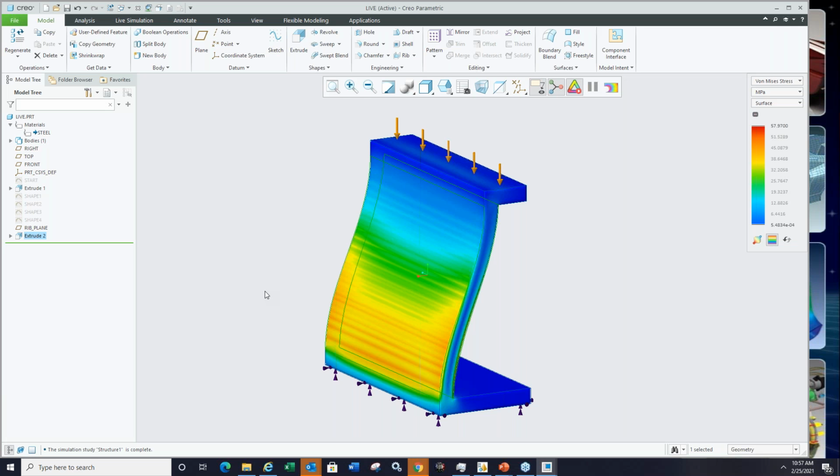So I'd say we have some comparison studies and everything, and it's within 10% on models like these. Time is the key here, right? On a large assembly in Creo Simulate, maybe you're running the multi-pass adaptive analysis for 3 hours. But assuming it's all bonded and no contact and things like that, which we don't support inside of Creo Simulation Live, you may be able to get that in 5, 6, or 10 seconds. It's more the time that is the key here, where you're able to get quick feedback.